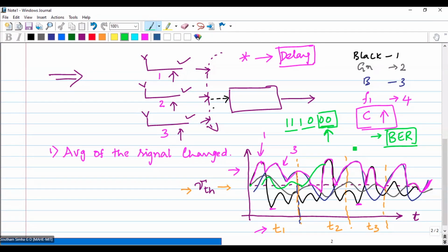Okay. Now look at the pink one. What is happening with the pink one? Now the pink line, if you follow the pink line, what is happening at the pink line is received signal strength, or it is also called RSSI, received signal strength indication. The fluctuation of the received signal strength is very less. You have somewhere like this and this and this, and so forth. Compared to the original branch, the fluctuation of the signal strength is very